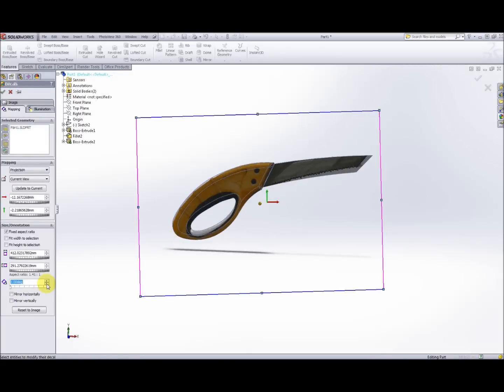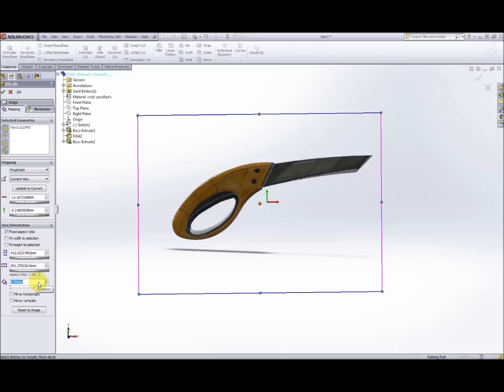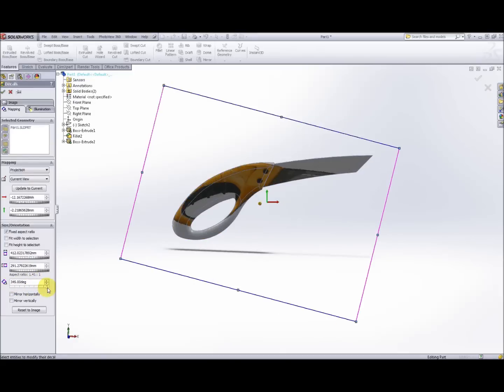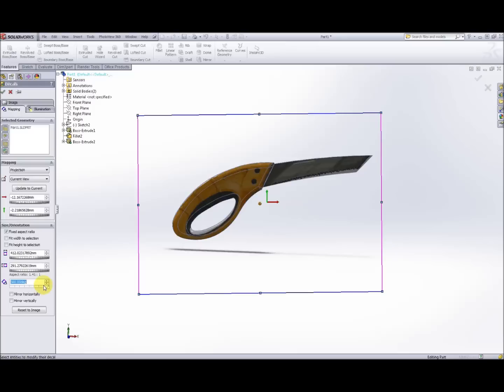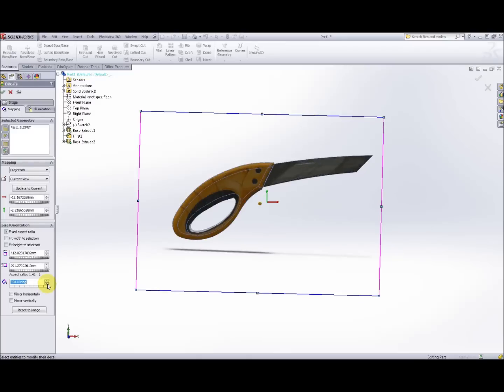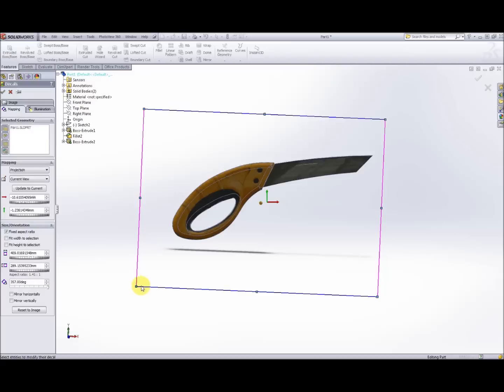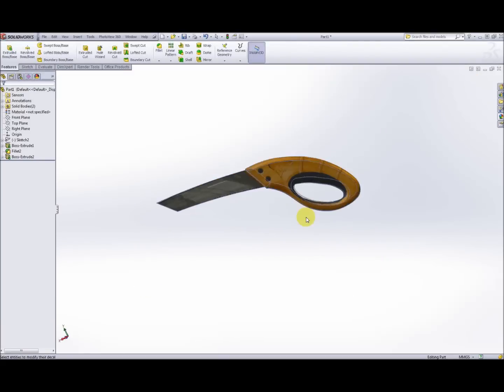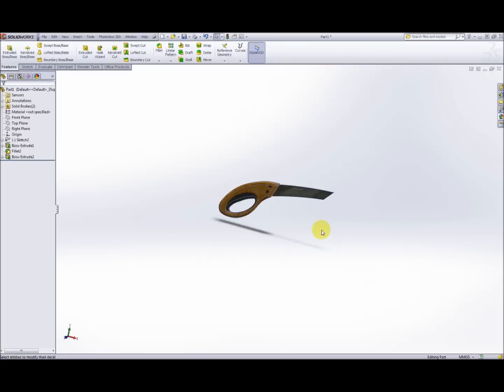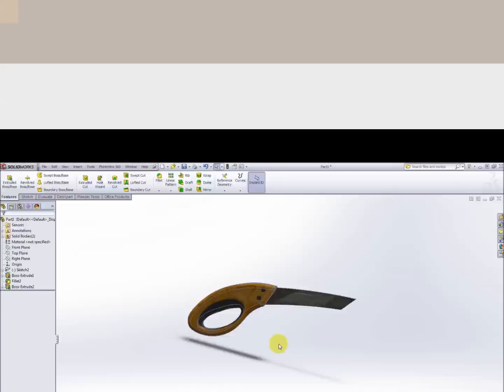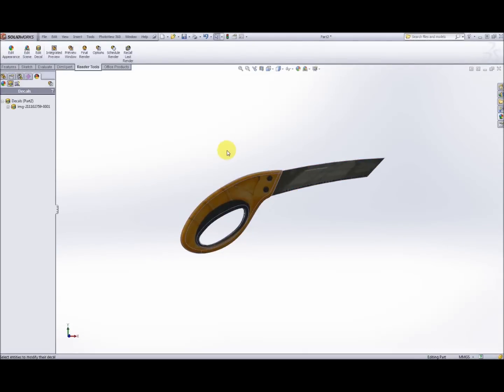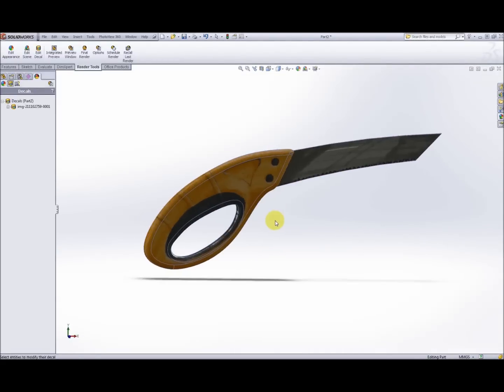I need to rotate that slightly. Now annoyingly it won't go negative, so you have to rotate it all the way around 360. So just play around with that until you get it to the right size and shape. Pull it and prod it and shift it, and hit OK, and there you have now a 3-dimensional view of your blade.